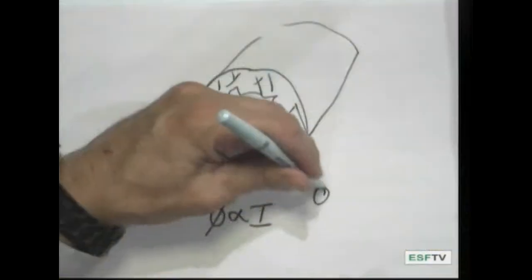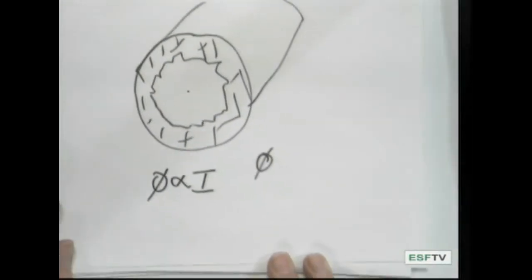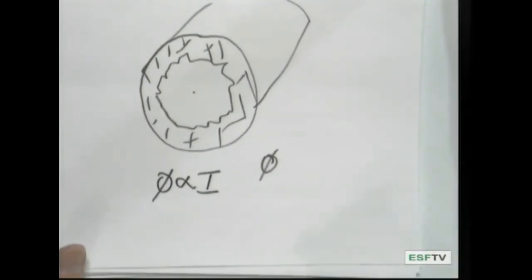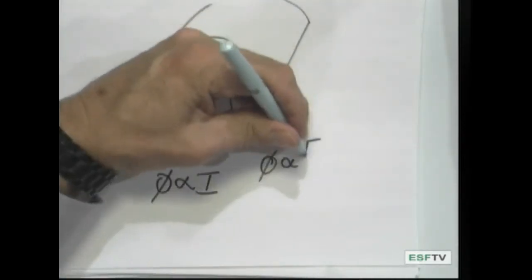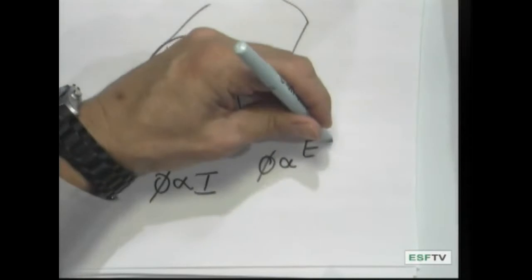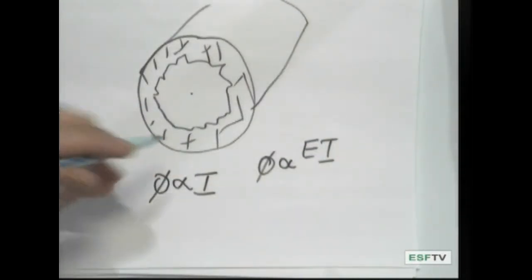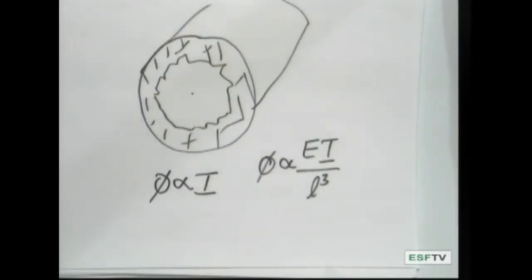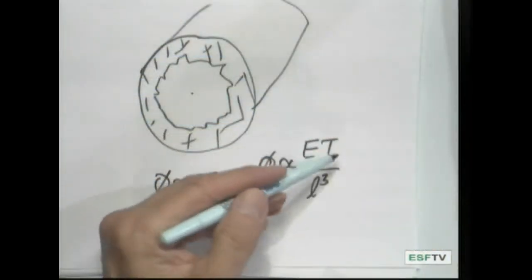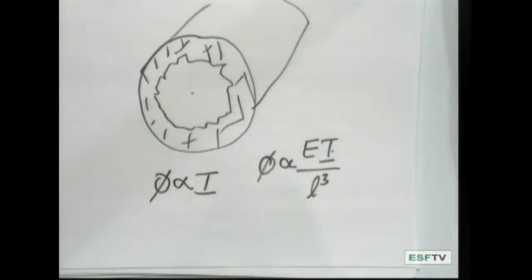Again, there's nothing complicated about this. We can look at our flexural stiffness and all the things that feed into it. In the case of our flexural stiffness, we are looking at a proportionality that considers the Young's modulus of elasticity, the second moment of area, over the cube of the length. And so what really determines the stiffness of an object is this product of the Young's modulus, the material property, and the second moment of area, which determines its distribution.